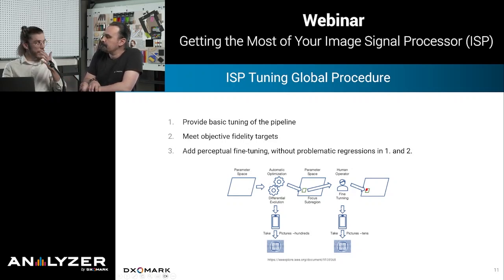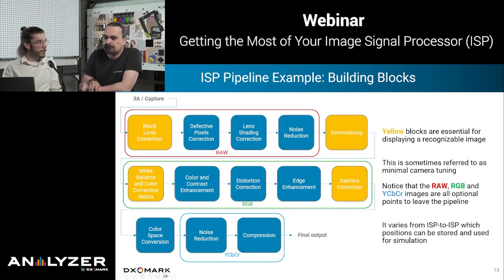So you're talking about a pipeline, yes. Right? So can you tell us a bit more about that? Yes, a pipeline is a very diverse set of possibilities in real life. So first of all, we need to understand that the term pipeline is a metaphor, an analogy. There is no actual linear sequence of blocks one after the other, like the one I depict here in the picture. It's a logical pipeline. Realistically, this is a certain number of functions that are implemented in different computational units of my system on chip, and that I'm going to call in a certain order to achieve a certain result.